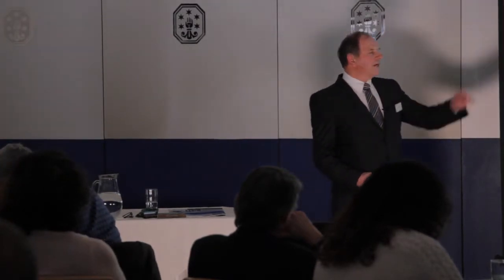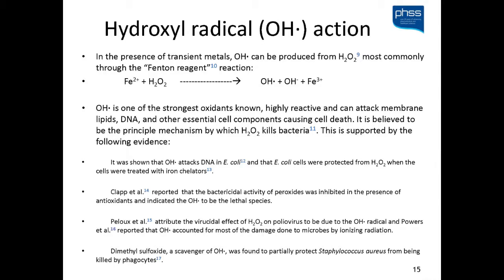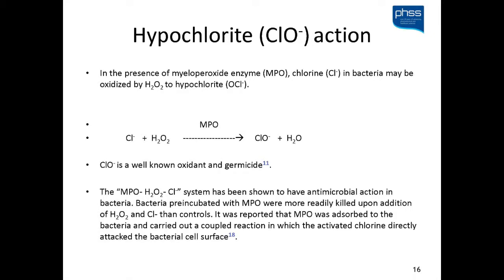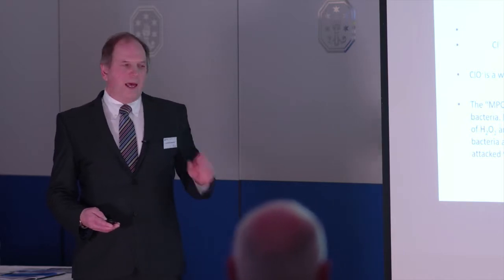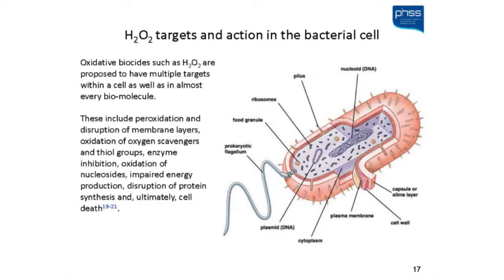And these reaction mechanisms actually take seconds. So why have we taken minutes or hours to do a decontamination when the mechanisms of free radical attack and reaction mechanisms are very, very short? And it all comes down to the presentation of the peroxide and managing a condensable vapor, reaching the saturated vapor conditions because we want to get past dew point, and then controlling that with good distribution. And those are where the challenges come in engineering integration. So these are the slides that just give you the background.